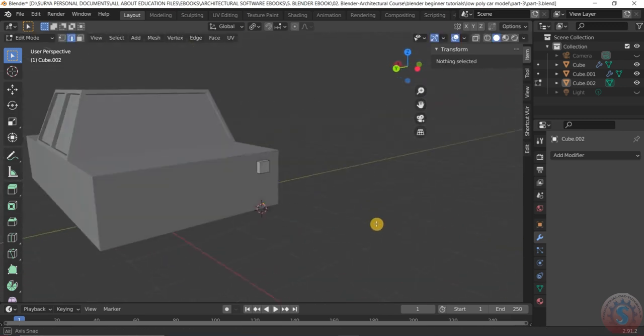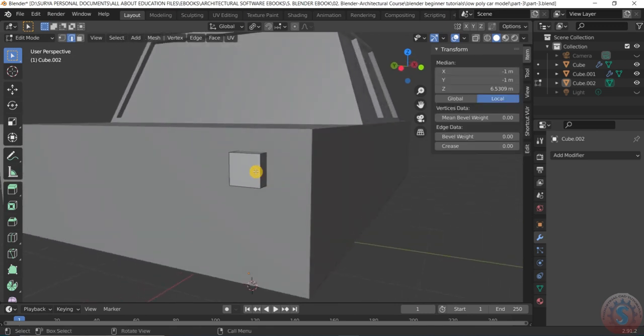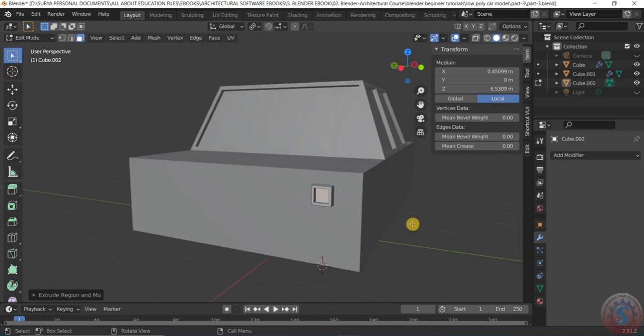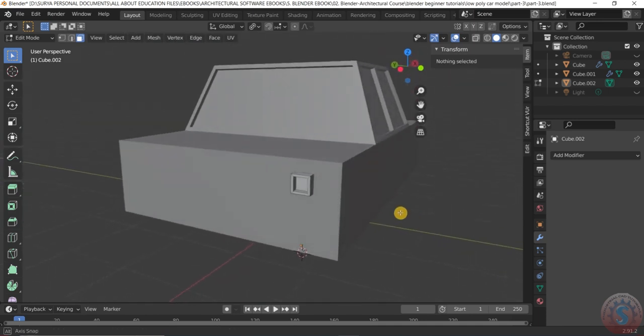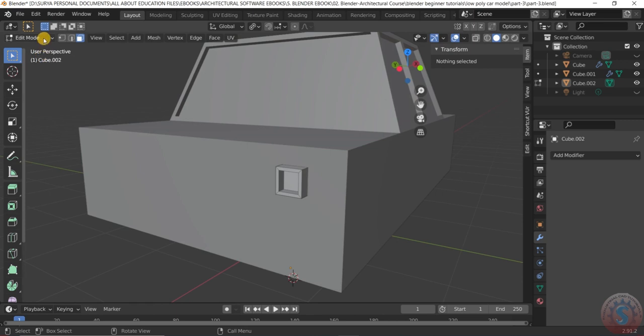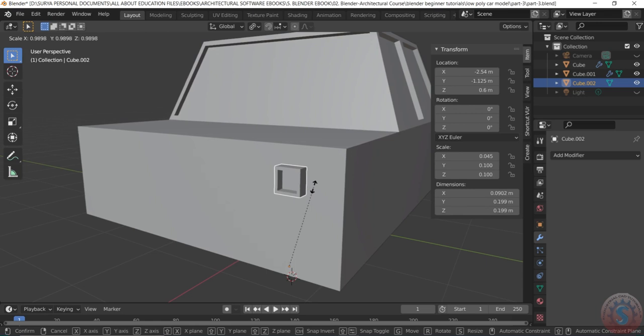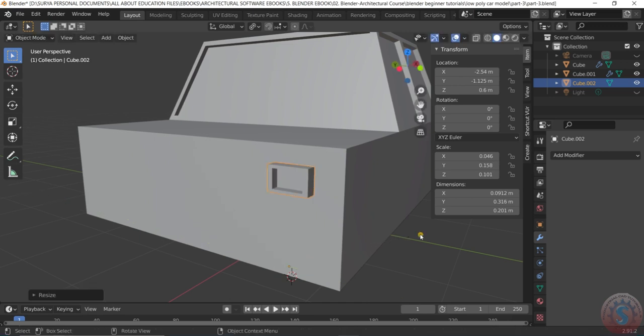like this. You can see I want to select the face by pressing on the I, insert this like this somewhat of a distance, and again extrude to inside, like this. You can create it by selecting on the object mode. You can also scale this to Y or X or Y. I'm increasing to Y somewhat of a distance like this.